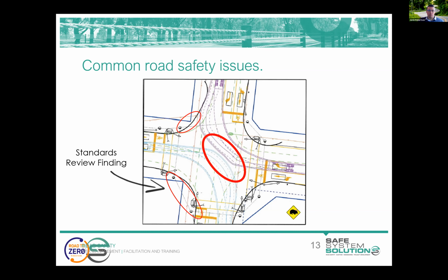Ensuring that the choice of vehicles for those movements is correct would be a first step. An alternative recommendation would be to ensure that the signal phasing, the intersection split phased or similar, ensures that conflict can't happen, or its likelihood is minimised anyway.